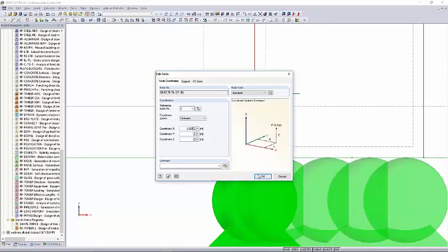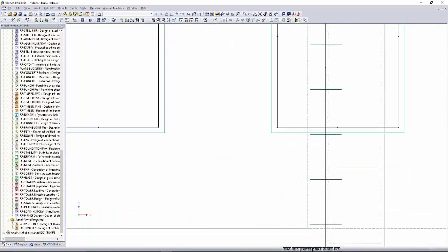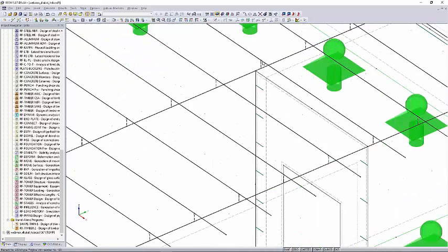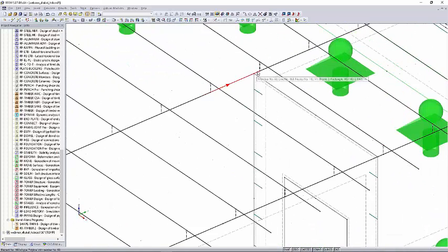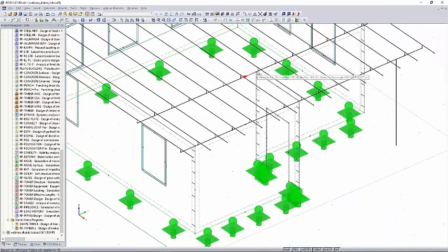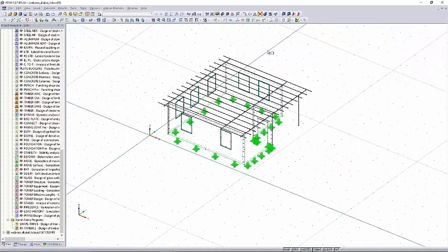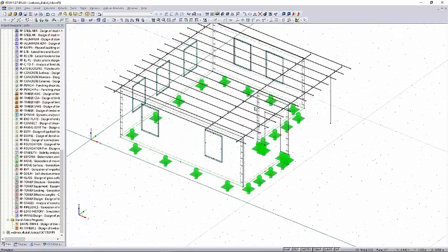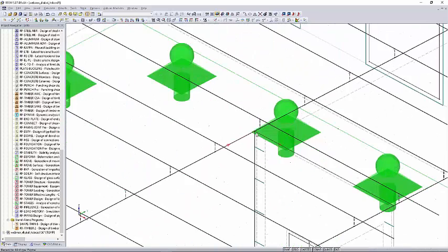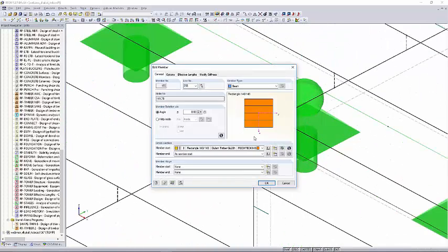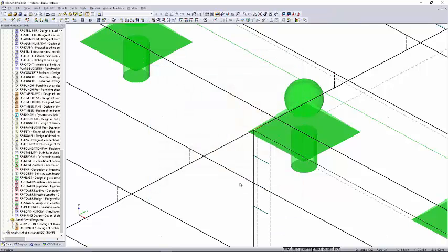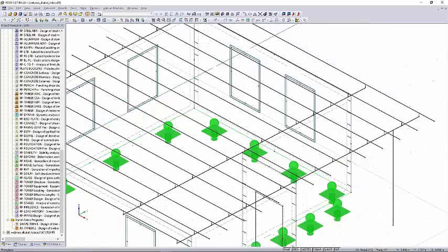X direction. Okay. So, and if you look at it now, you see that, oops, no, I was here. That looks much better. I will probably have a pretty high load introduction here. I will show you also a little trick how to avoid that. At first I will connect all the lines together so that they are really integrated into these elements. So if you look now, it is completely integrated there. And here I will actually make a small moment hinge as well at the end, just to not have such a high load introduction here into the structure.